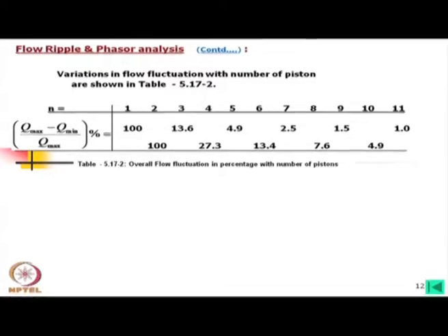Why 5? We should go for 13, but you should always remember, with the increase in the number of pistons, the cost will increase. Valve porting will be a problem, the second problem. Thirdly, in terms of reliability, when they start to have a little error, the dynamics will increase in case of a larger number of pistons. After a certain time, you will find all the pistons and cylinders are not of the same size. Within the tolerance zone, they are different. Now, when they are worn out, if there are more pistons, the dynamics will increase.